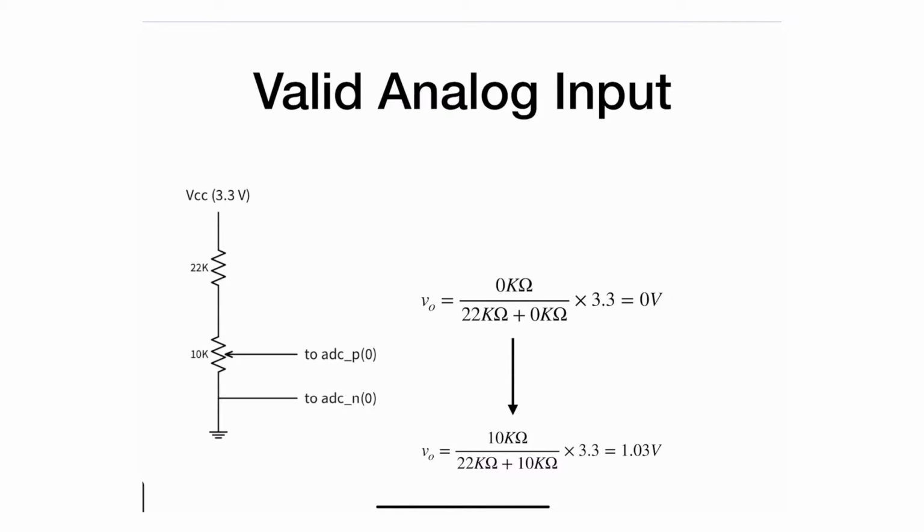These are not the only values that you can have. You might have it differently, but just make sure that on the ADC input, the negative part should be connected to 0, which is ground, and the positive part should be connected to something that can go all the way up to 1 volt. If you're using 22K, it's up to whatever you have. I have something a little bit different, and I'll show you shortly. Okay, so now we move into the test program to see what we can do with it.